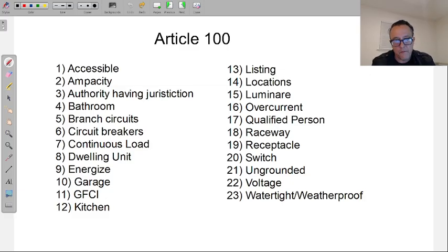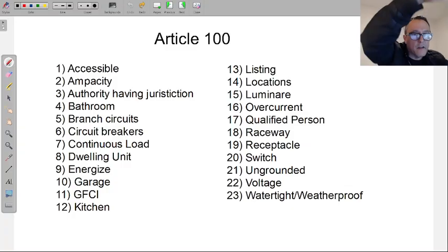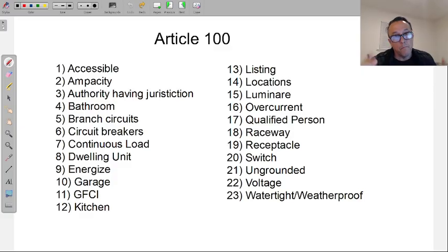These are just some main points that I've seen before too, and noticed from job sites, where I've seen these things come into play. I saw that one accessibility of the wires argued in a lobby of a building once. There was an access door, but if you looked inside that area, yes, you have enough room to crawl as a human, but there was an AC duct running through the whole thing. So you can't get over the AC duct. But the contractor was like, well, the AC duct's not my problem. It meets the code. And the inspector was, I'm not having it. That's where it ended. All right, so one word, accessible, out of the way.